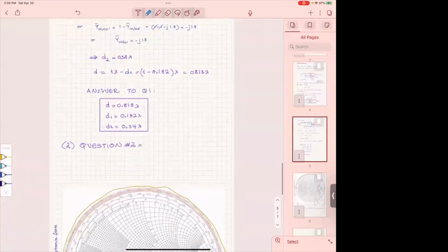So here we are going to have the source, V sub S. We are going to have the internal admittance of the source, Y naught. And then we're going to have here the admittance that the source sees at AA prime, which is also Y naught.